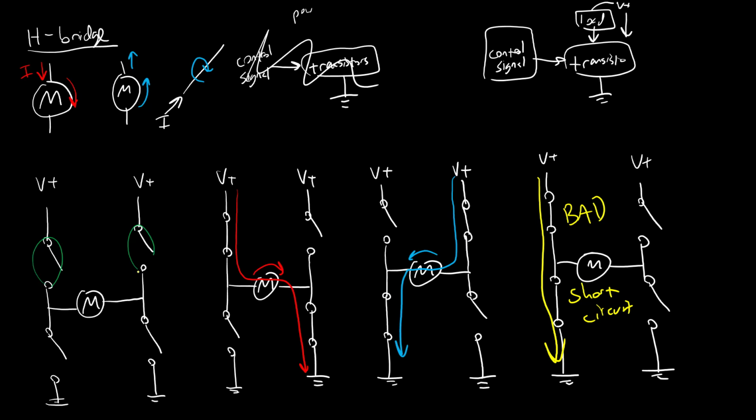If I imagine each of these as a transistor which has a control pin, again, either the gate of a MOSFET or the base of a BJT, where I now have a control signal, either a voltage for the MOSFET or current for the BJT, controlling a larger current, it acts like an electronically controlled switch.